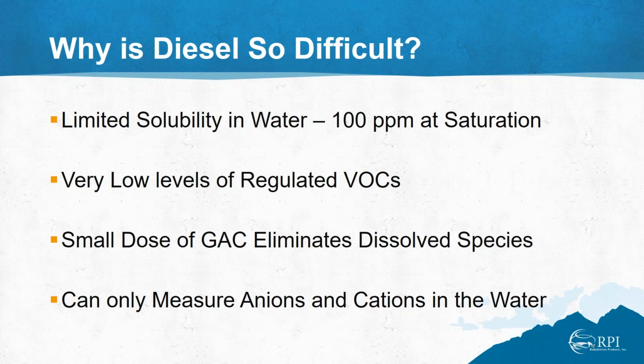The other difficulty is that even if I prepared a water solution, say 50 ppm of diesel fuel in water, a very small dose of activated carbon literally eliminates everything from the water. So you're only able to measure changes in anions and cations in the water.